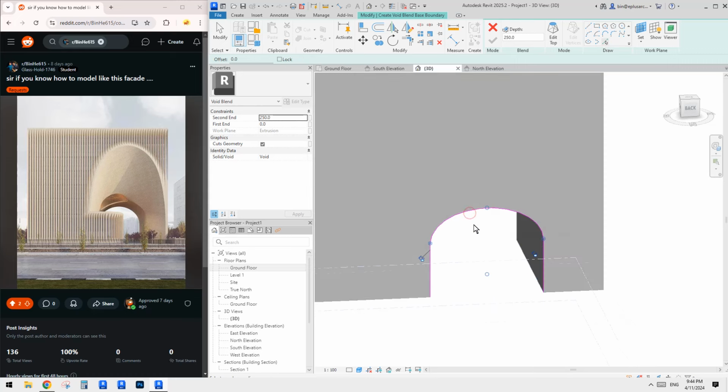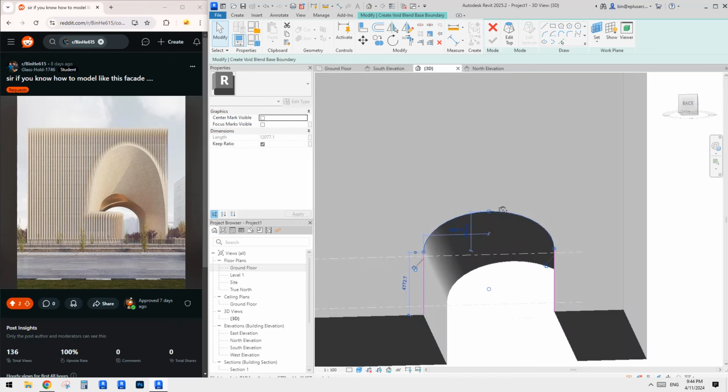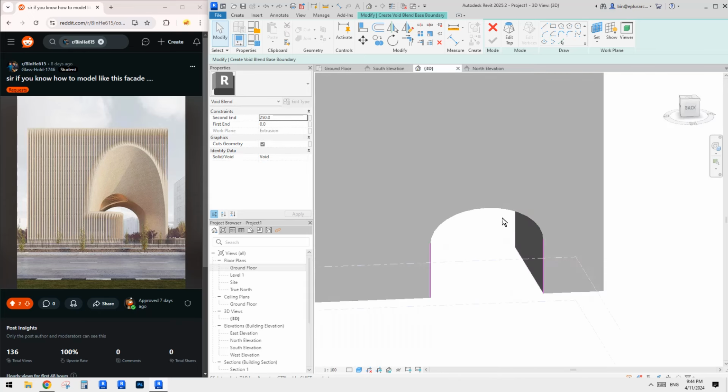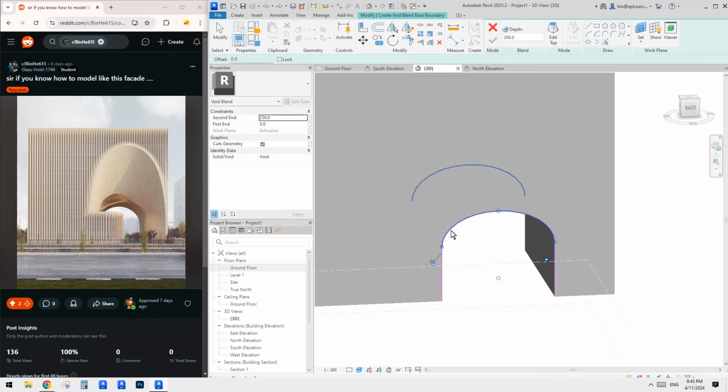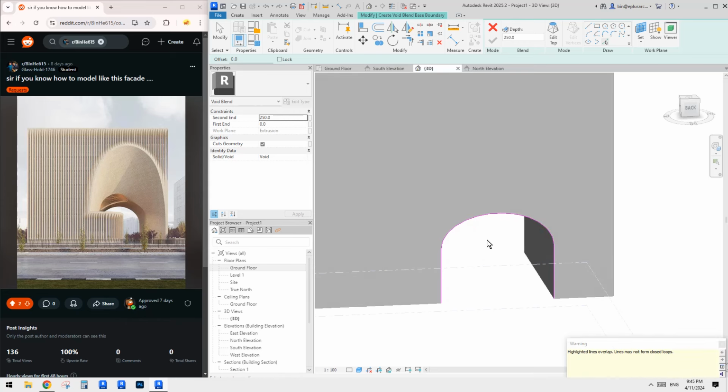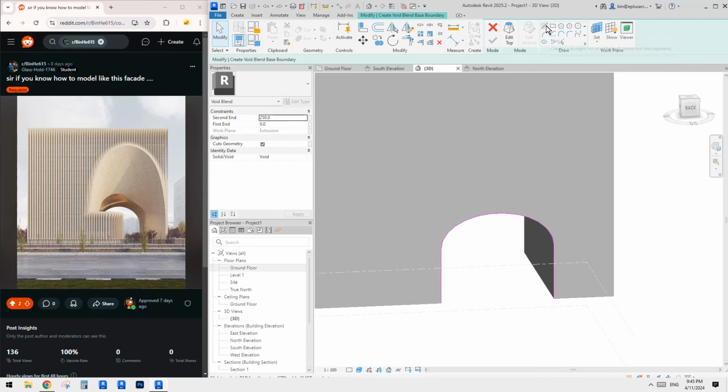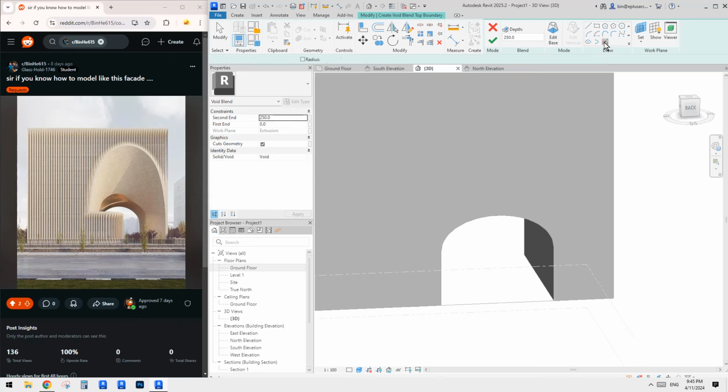This one's a little bit tricky. Oh, great, it's okay. Sometimes when you pick an ellipse edge, it becomes a spline, but this one looks fine. Also we need to close it, right? So close it, and then edit top. We need the second profile. This time I'll just offset. Not sure how much, but let's try. How about 2 meters? Roughly. There, we need a little bit more. 3 meters, I think that's probably enough.